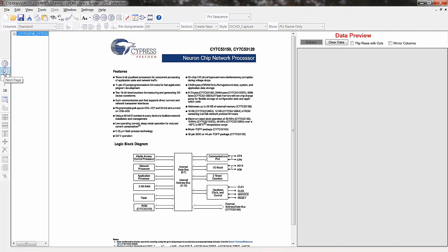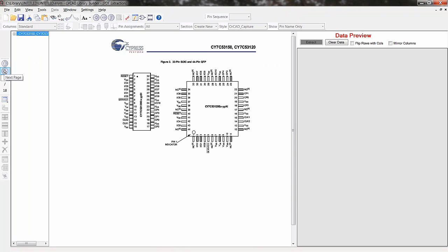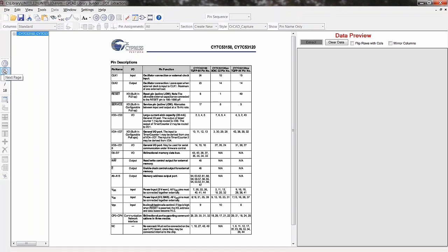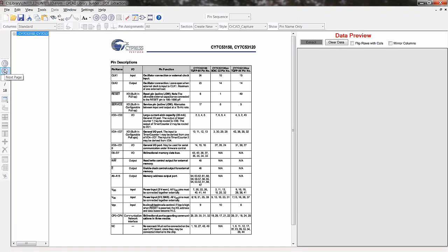So what I can do is get back over here and browse for the information that I'm going to extract. And remember from the slide presentation, we could extract things like tables, we could extract graphical views like this. Whenever you have the option to do a table, that's my suggestion, because there's more information in the table than there is in one of these graphical views or a bitmap of a BGA. So when you can use tables, do that.